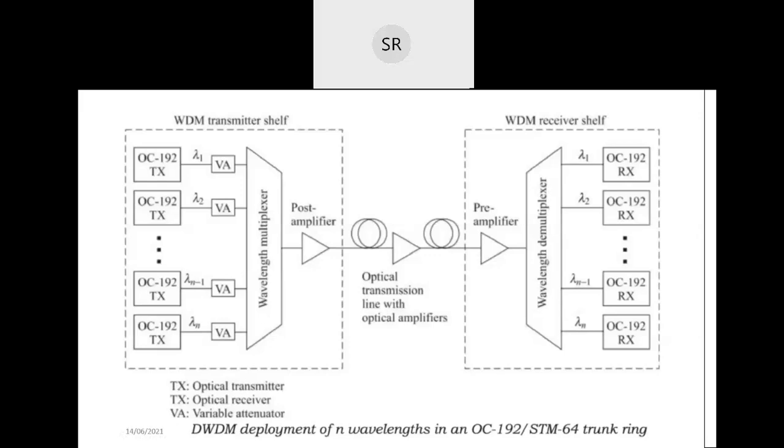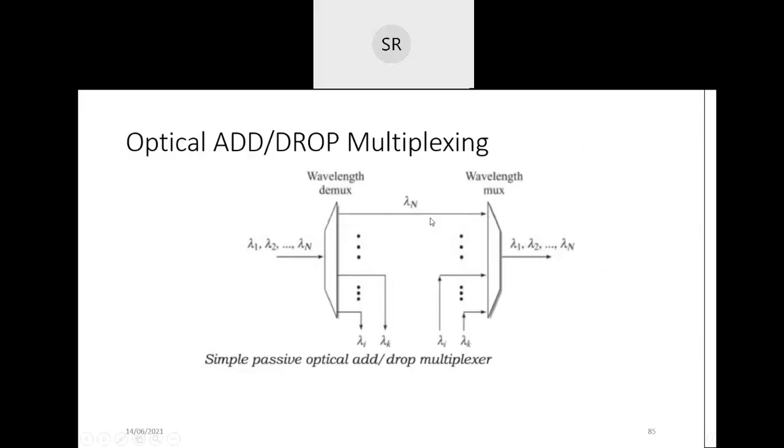For combining these multiple wavelengths into the given optical fiber, when we combine all the channels, at the input end of the optical fiber they should have sufficient optical power. If the optical power is too large, then there will be scattering. If the optical power is low, then we use an amplifier and then transmit. So we need to use sufficient optical power for transmitting the signal from one node to another node, that is, over a link.